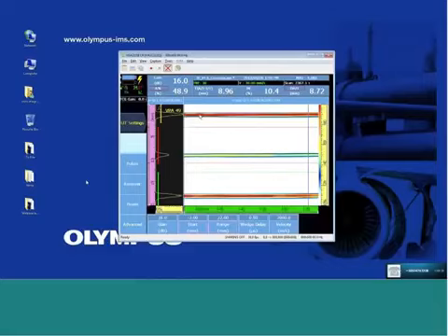One of the big benefits to a water wedge, like the hydroform or an immersion tank or some other custom wedge, is that the interface signal compared to a wedge is fairly small. In this case, up into about 1 or 1.5 millimeters, I have a very good detection on the interface. So my ability to detect very small defects near the surface or pitting or even corrosion right up to the surface is enhanced by a small interface signal.